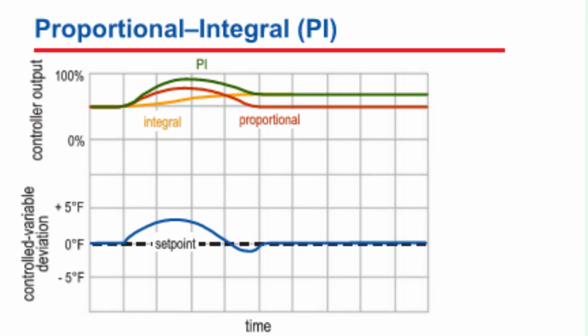Here, Kp is the proportional gain. It sets how strongly the controller reacts to the current error. Ki is the integral gain, or 1 divided by the integral time constant, Ti. The term integral of error means the controller looks at the accumulated error over time, not just the present difference. Most commercial HVAC systems use PI control. It's stable, accurate, and energy smart.